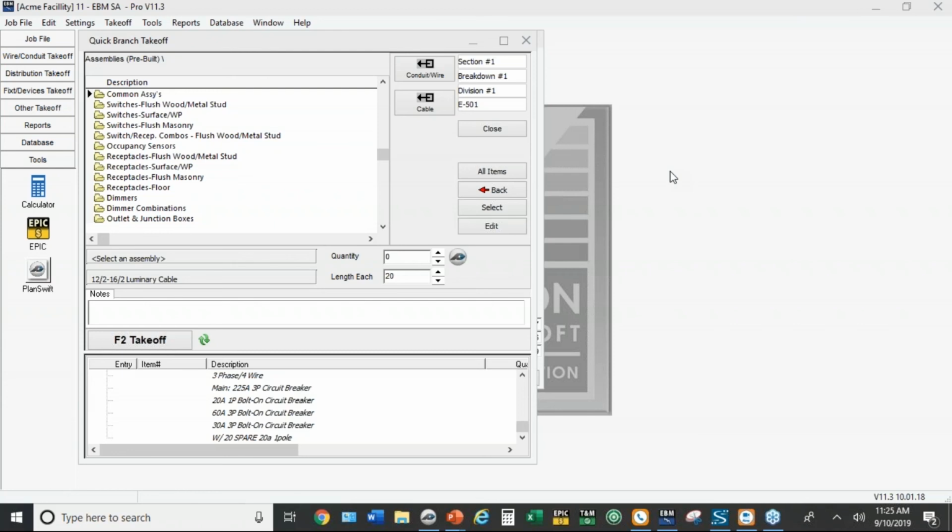Would you do the same for mech EQ branch? Mechanical equipment, yeah, only if it's 20 amp. Anything that's 30 amp and above, I would definitely measure the home run. To me, most of the mechanical is really like a mini feeder, whether it's a 30 amp, 60 amp, 100 amp, 200 amp mechanical item, that definitely needs to be measured. You got to pick up usually a safety switch and motor connection and the home run. So that's not where I would take shortcuts.